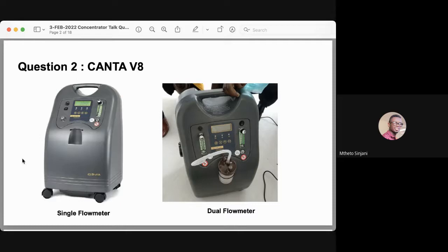This will be an indication of how worn the caps and the sleeves are inside the compressor. Every compressor will be equipped with a pressure relief valve. If the compressor is strong enough, it will cause the relief valve to activate, and it can be easily heard. So at this point, the pressure gauge should be showing at least 45 psi or 310 kPa. So if you are successful with this first step, then the next step is to check the solenoid valves and